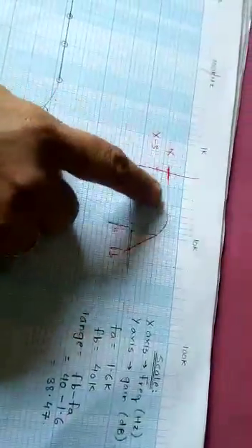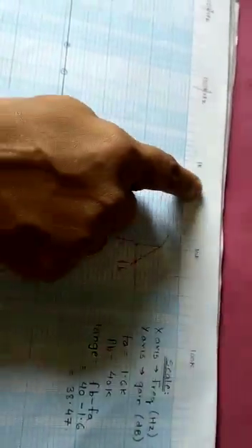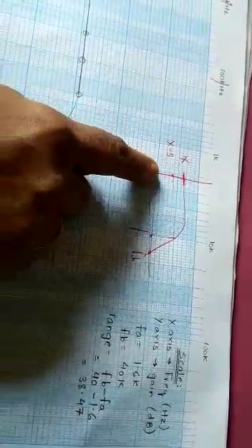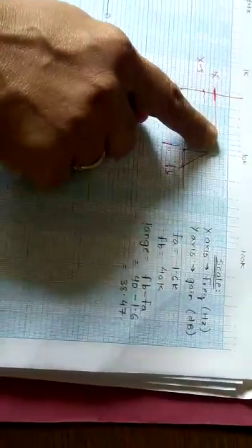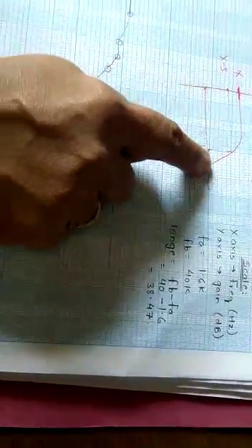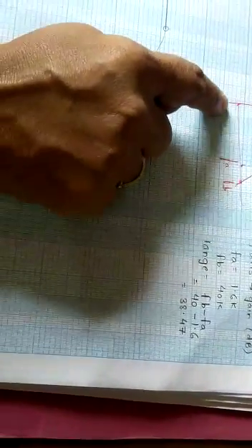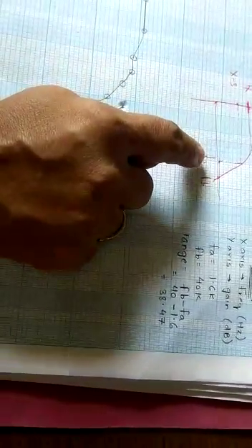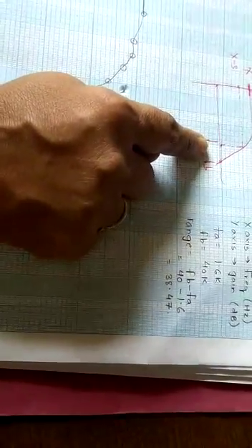So I will show you the standard frequency response over here. On the x-axis we have frequency, on the y-axis this is your gain in dB. Up to FA, you can see here we are getting a constant amplitude, and after FA it drops, and when this magnitude plot cuts the 0 dB line, that is known as your FB frequency. Up to FA your circuit acts as an inverting amplifier, and between FA and FB your circuit acts as an integrator.